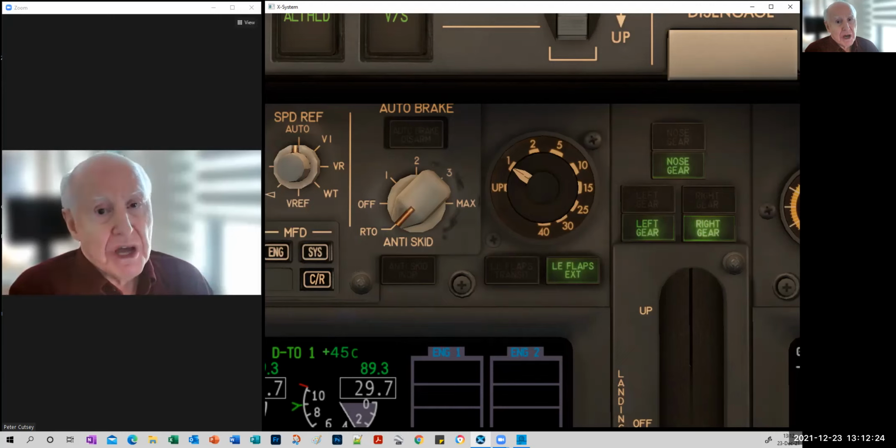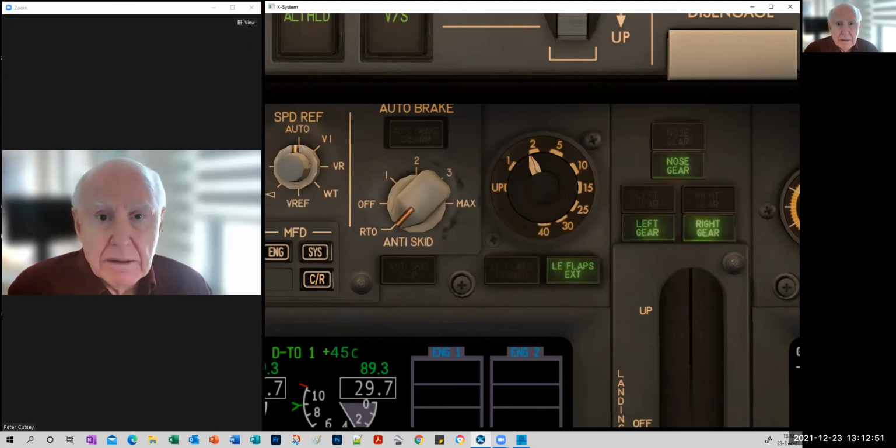So for our exercise today, for the first part, for the IFR portion, when you're downwind, you'll see the runway on your left-hand side. Will be on the north side of the field for vectors. So when you're downwind, call flaps 1 and set flaps 1 speed. Pilot monitoring will do that for you. As you're turning base, call for flaps 5. And once you are at flaps 5, set flaps 5 speed. Pilot monitoring will do that from the speed tape.